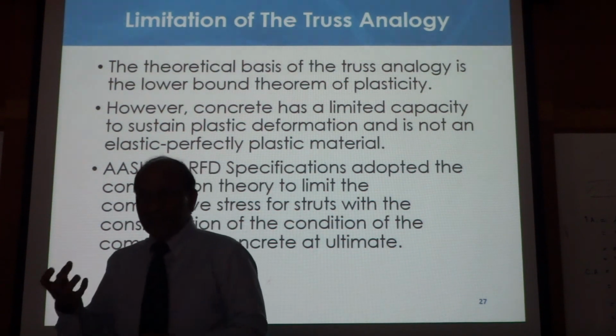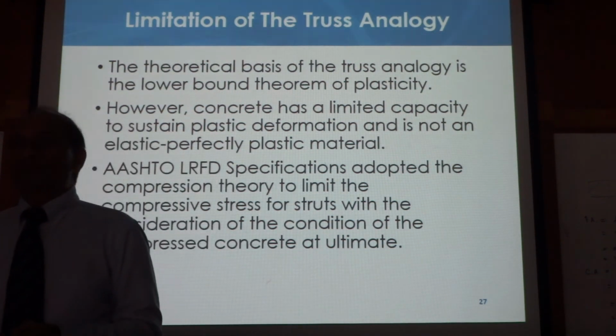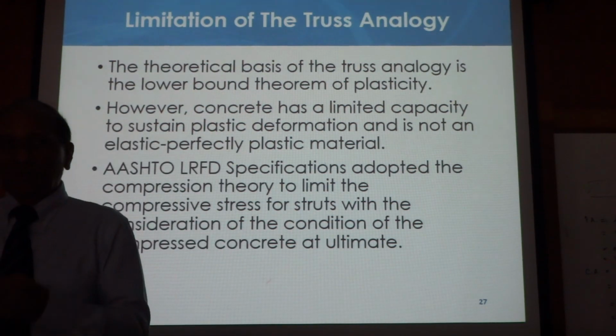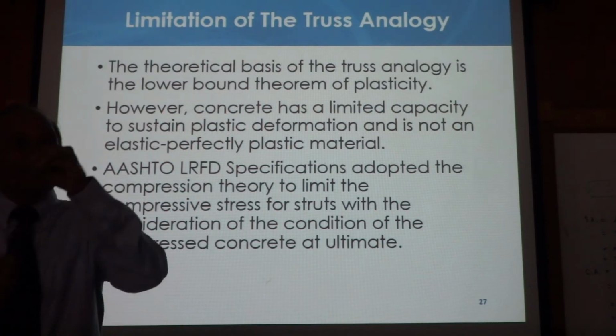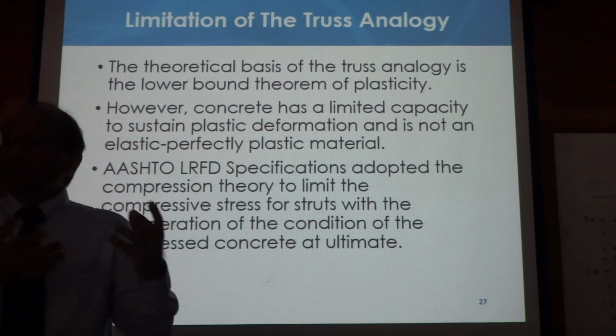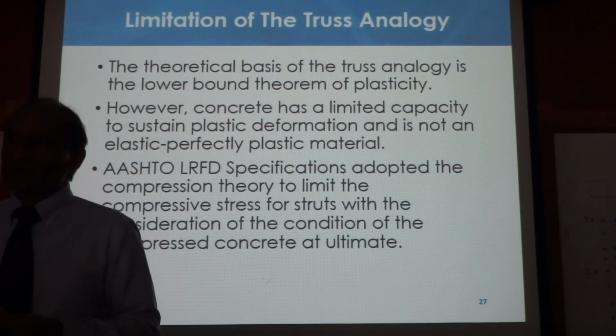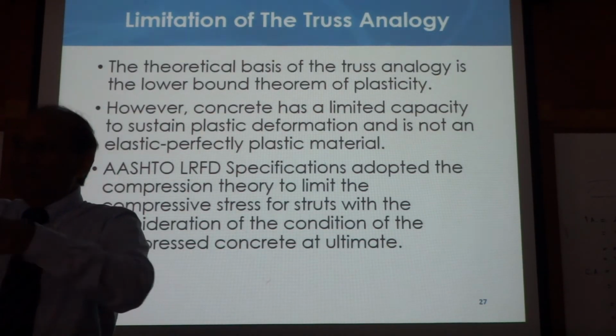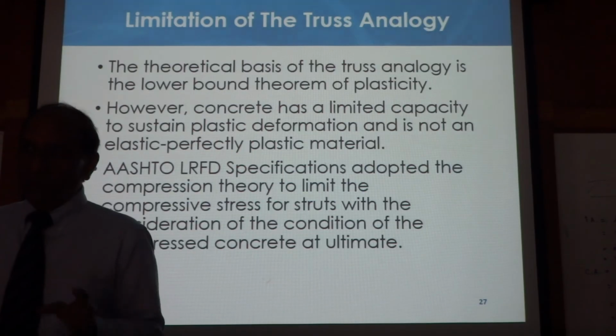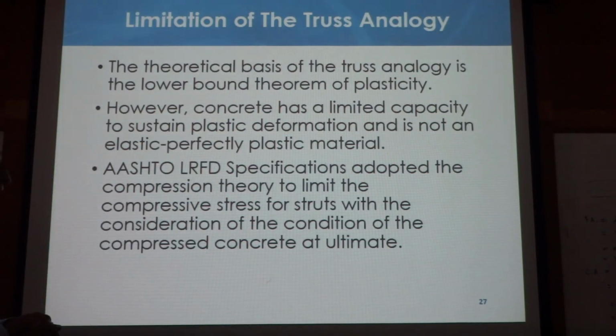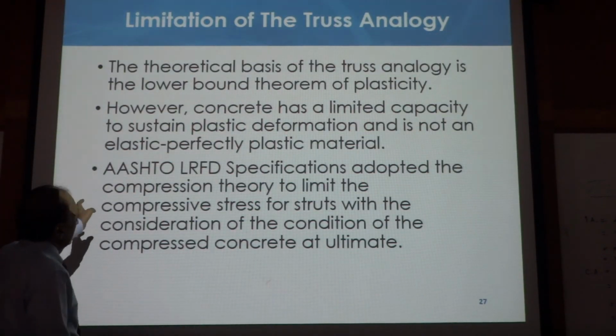So that means large cracking, we cannot predict what happens after that. Because once we give all the tension to steel, steel can yield easily. So what is happening in the concrete then? We don't know. Concrete cannot just let the steel yield and stay quiet. It has to also deform with that. So we do not know the large deformation, this is not good.